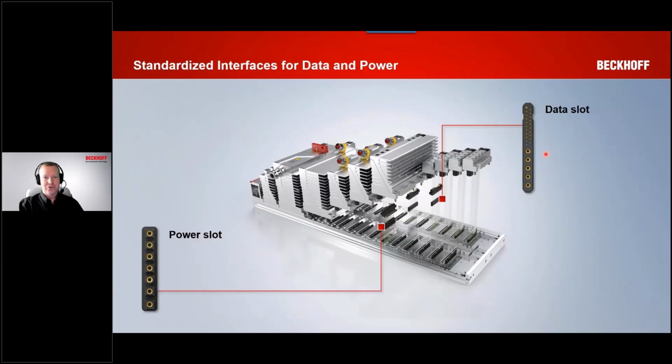It distributes our 24 volts and our 48 volts in parallel across the base plate, so that that's available if we happen to have the 48 volts. Having that across the whole thing in parallel with 24 is a big deal. And then on the power slot, it's the same concept. It's your three phases of your 480 volt with neutral and ground available, and your plus and minus DC for high voltage DC on that power slot, distributed across the entire base plate.